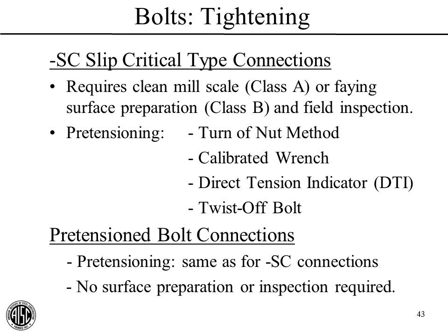And you can see that 3 of the 4 methods here still use the general method of going from torque to axial force, but they're very particular methods that are established and well documented, and they're prescribed in the RCSC spec.